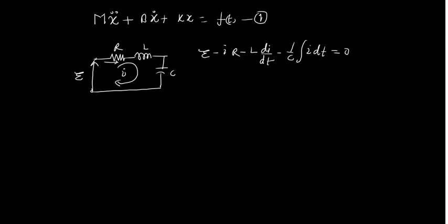So one thing is that we have to get some differential equation like this. One relationship we are having: what is that? i is equal to dq over dt. So can we substitute this i wherever required? Similarly we can write q as integral i dt is equal to q, of course from minus infinity to t. So just substitute this equation into this one.